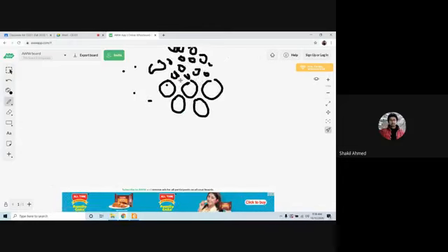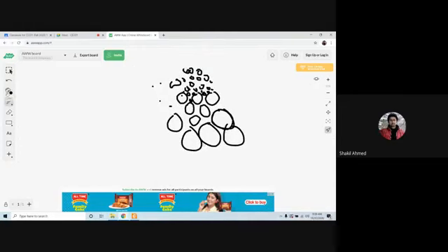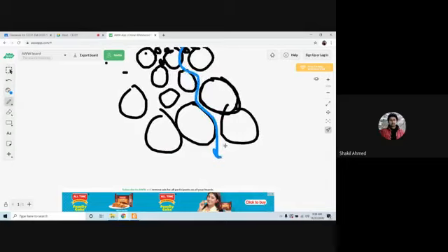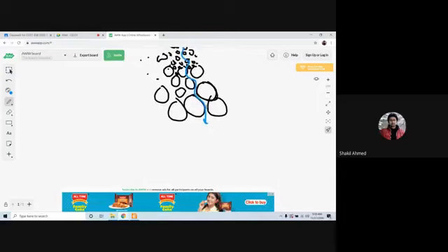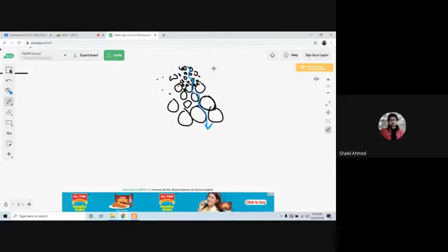So now these particles will be resting upon them, right? And then again larger particles. So these particles will now be captured by the even larger particles. And finally, as the water moves, you'll get clean water, and these smaller sands will not be able to come here. You'll get clean water. Is it clear? Yes, sir. That's why you arrange the gravels from smaller to larger size.